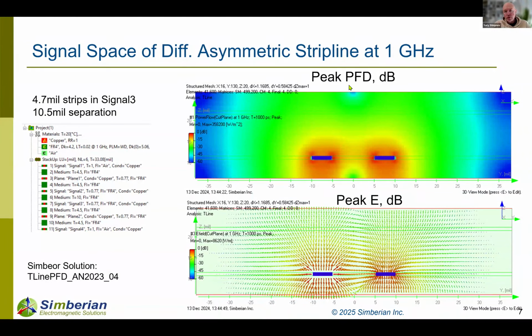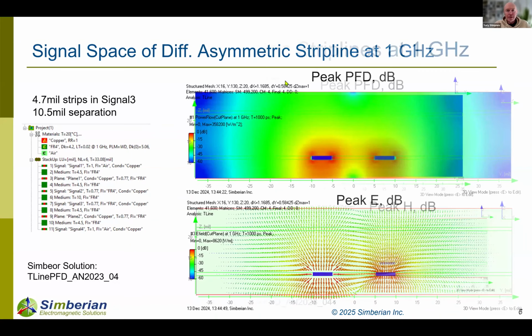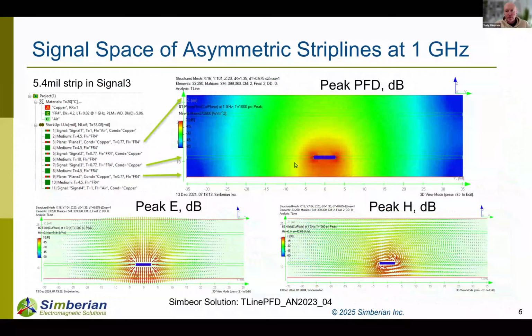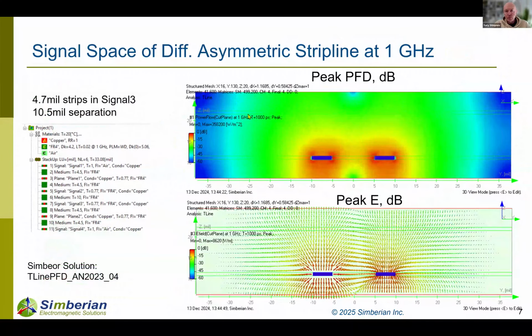So this is an illustration of the differential case, and this is an unsymmetrical strip line. If you start moving, usually we assume that all the currents are going through the closest plane, and that energy is localized somewhere here. It is partially true. You can see that this red area, where most of the energy propagates, is quite localized.